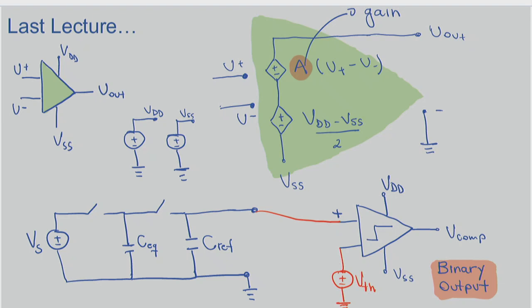So we looked at how inside the operational amplifier, we had these two dependent voltage sources, voltage-dependent voltage sources, and one of them was defined between VDD and VSS, where VDD and VSS are independent power sources that we add to the amplifier in order to define the rails of the amplifier, the limits of which the voltage levels we reach when we use the amplifier.